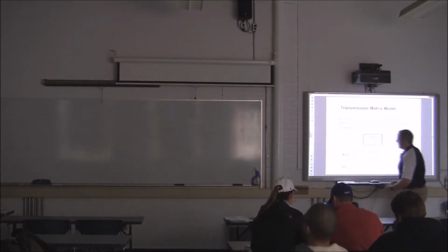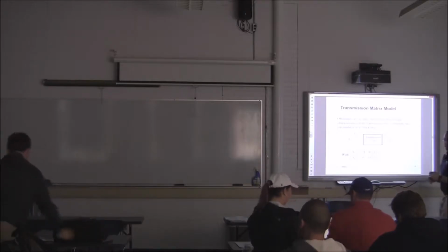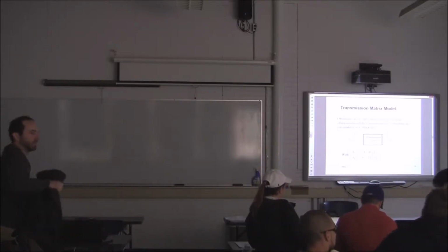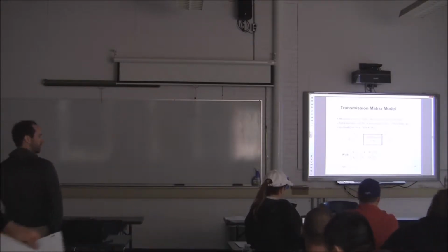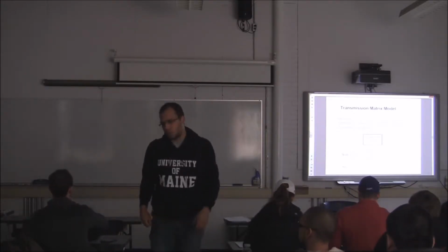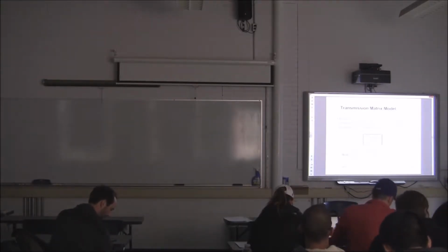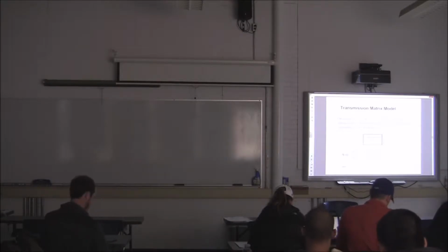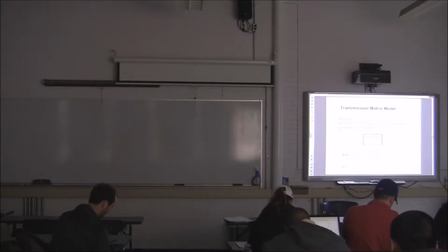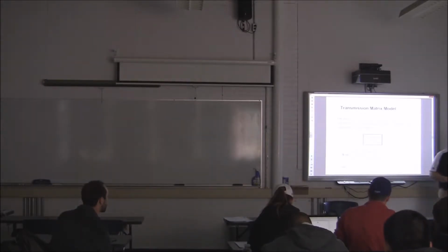And there, good, okay. So we were talking about transmission line quite a few classes ago, and we've got exact models of transmission line based on a unit length. So we saw how we could write a couple of differential equations, and the differential equations consist of hyperbolic sines and cosines, but ultimately we are solving for the sending end voltage and current. If you look at the previous equations, we came up with a way to solve for Vs and Is based on knowing what VR and IR is.